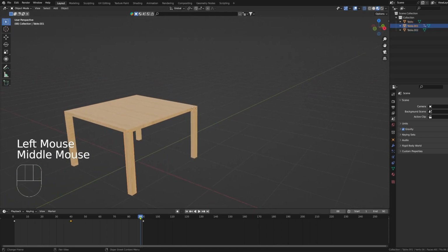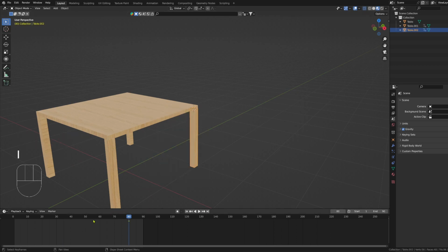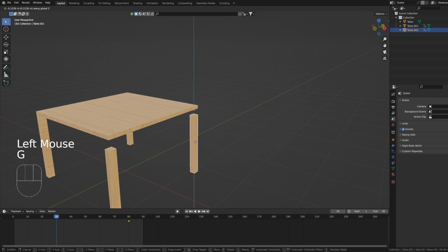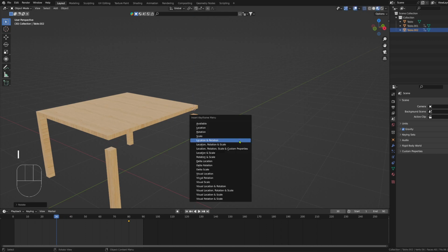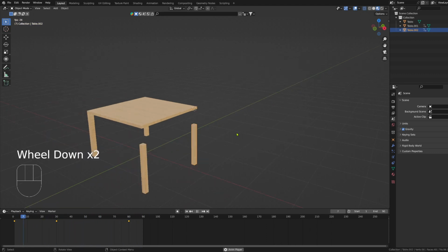And maybe you want a slight offset this time, so this leg installs a bit quicker than the other. So you can start maybe at the 80, location, rotation, and then this time I'm going to move it back somewhere 30. Down here, rotate on the Z, 720 degrees, I, location, rotation, go back to frame 1 and just drag this down. And that's the start frame. So now if I go like that, it's slightly offsetted, but I could have done a better job.